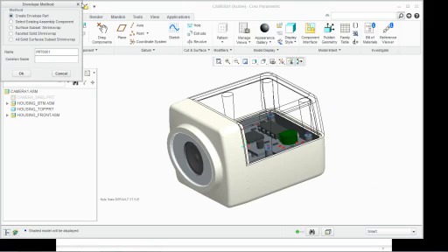You want to make sure you select all of the components in an assembly because then the envelope that I'm creating will allow me to substitute for the entire assembly. If I don't select all those, it won't allow me to substitute it for the entire assembly. So now that I've done that, I want to click All Solid Surfaces, subset Shrink Wrap, and I want to assign it a name, Solid Cam ENV for envelope.